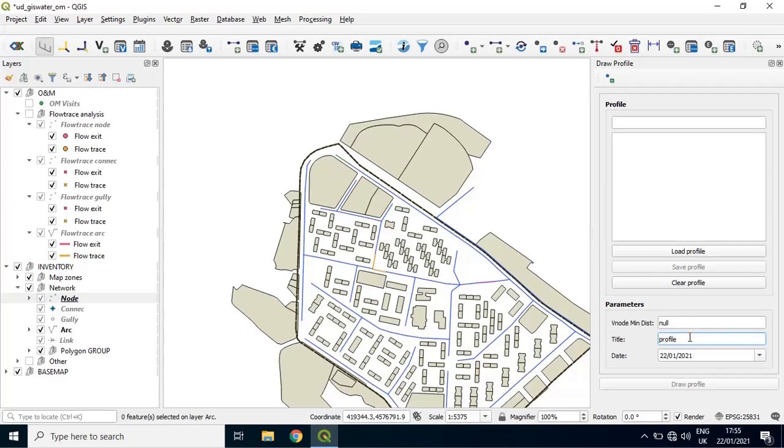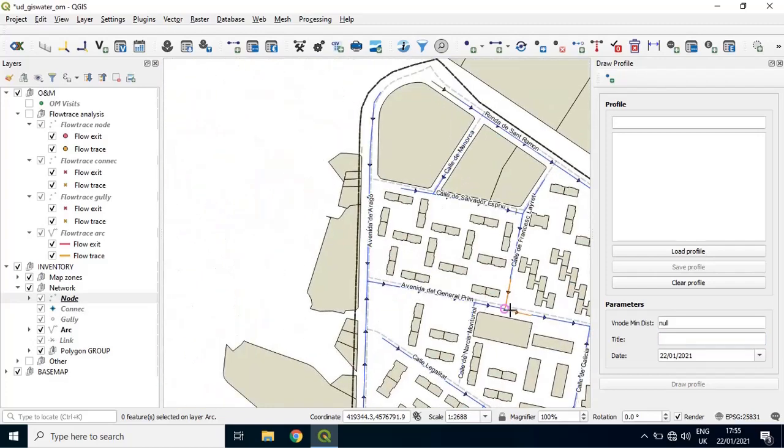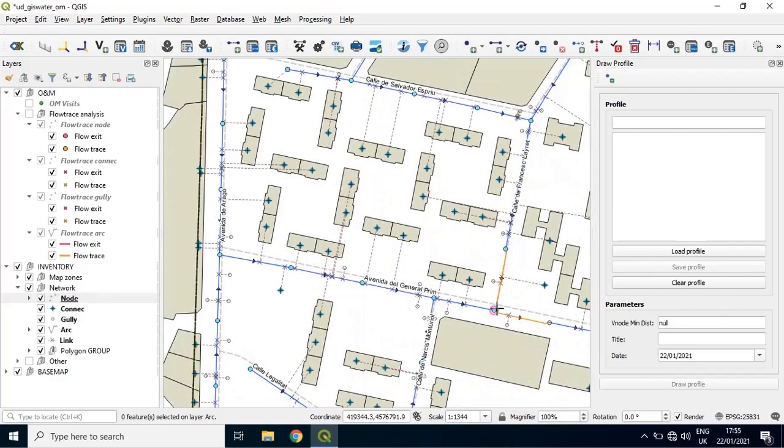In addition, there is an option of selecting an additional manhole which, in case the initial and final manholes have two possible routes, will mark the direction by which the profile should be drawn. The user can, optionally, establish a profile ID. With the button in the bar at the top of the form, you can choose by standing on top of one and clicking, and then do the same in the second.